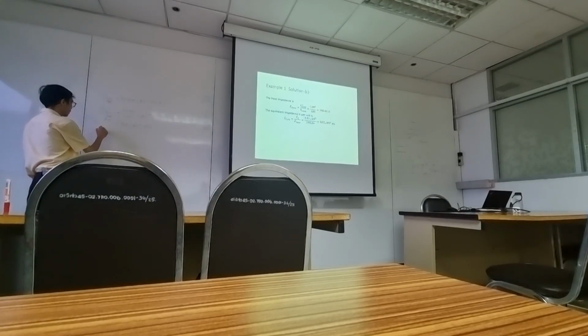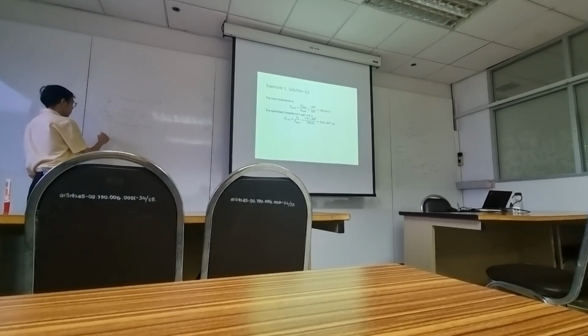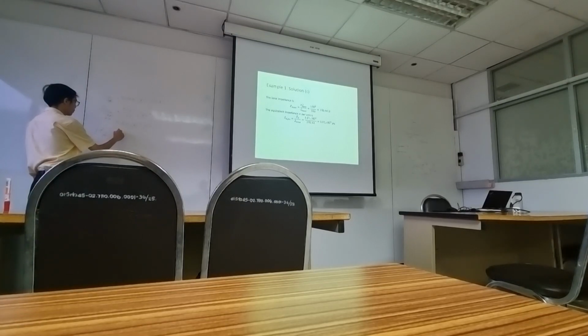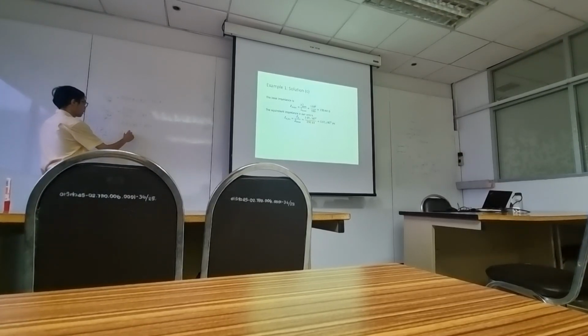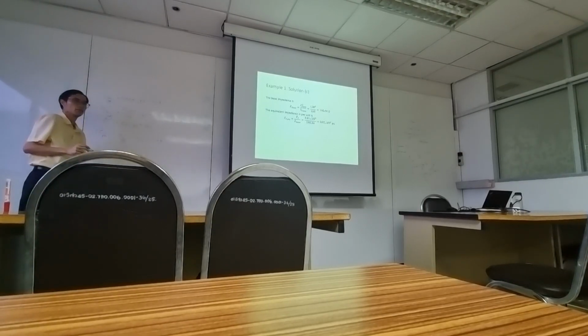You can see that ZS, the magnitude in per unit, would equal 1 over the short circuit capacity, 3 phase and also in per unit. So it is 1 over 50, and this is 0.02.